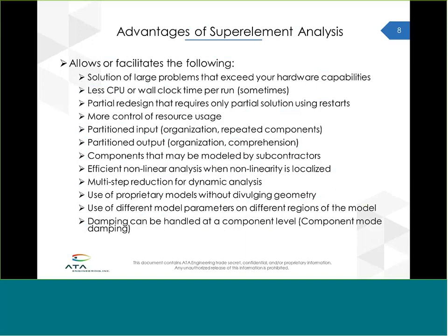You partition the model, make a reduction of each portion of the model, and then couple them all back together. And when they're all coupled back together, you can then solve your system model. It seems like this is less of an issue these days, but it's just something to keep in mind. If you don't have huge computational resources, then this can enable you to solve larger models than you would otherwise. You can sometimes reduce the amount of runtime, again, if you do this in a strategic and smart way.